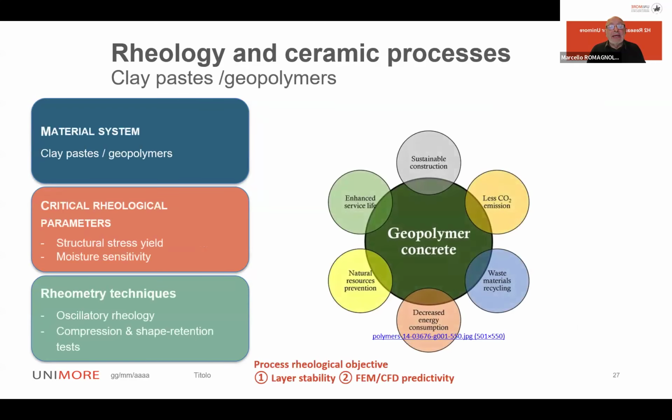And finally, if you want to study, for example, geopolymer concrete, the rheology is similar to the rheology that we use for cement, but we can also use oscillatory rheology just to study the kinetics of the reaction in the geopolymer during the increase of the mechanical strength, the mechanical characteristics of the geopolymer.